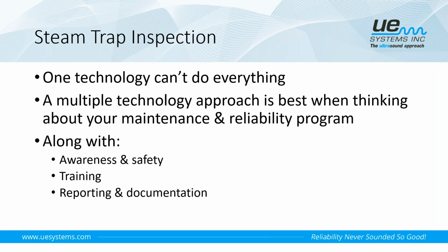Training: we want to make sure that the personnel responsible for maintaining our steam systems, maybe even doing the steam trap inspection itself, are properly trained not only on their ultrasound equipment or their infrared or temperature equipment, but also on the different types of steam traps, what their operation is, and what their sound characteristics should be when we listen to them with ultrasound.